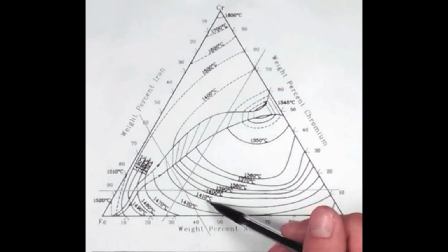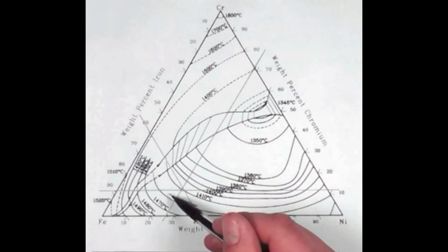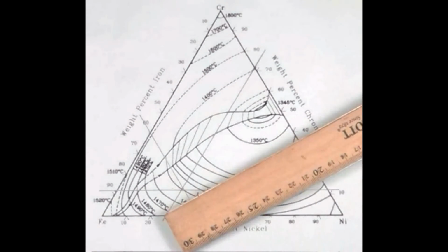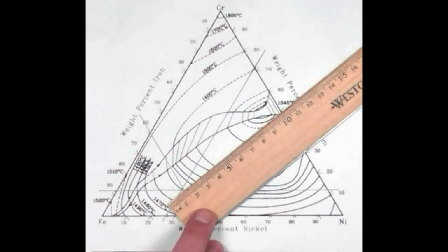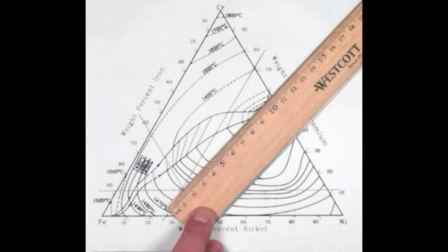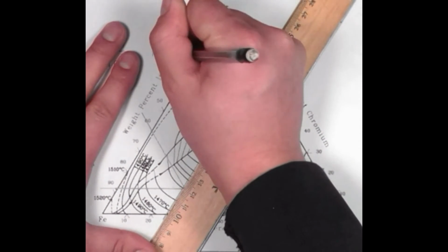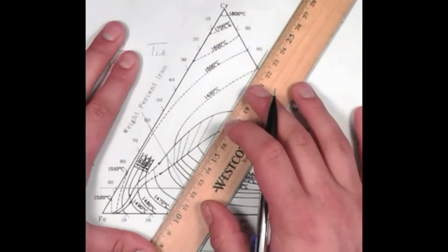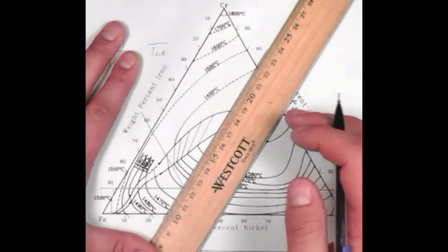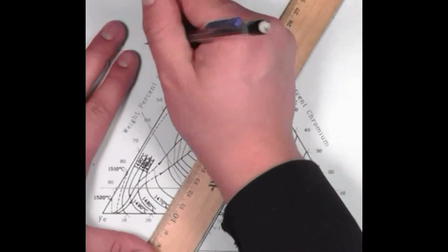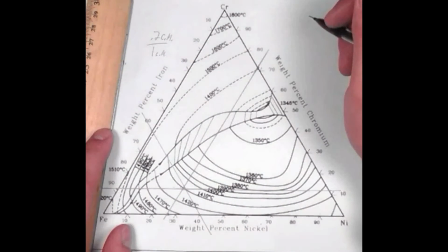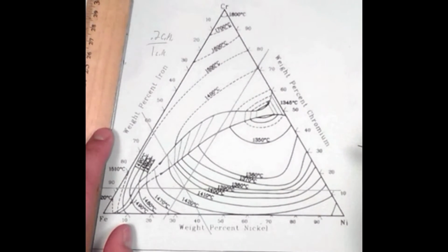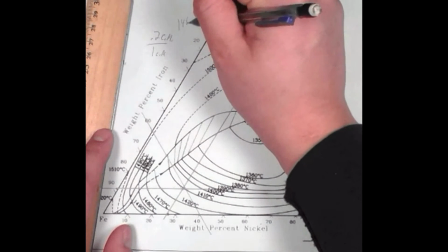As you can see, we were slightly over 1410 degrees C. If we want the exact temperature, we'll take a perpendicular line in between these 2 points and interpolate. The distance between our two liquidus lines is 1 centimeter. And the distance between our point of intersection and the 1410 degrees mark is 0.2 centimeters. Therefore, in order to obtain the desired stainless steel, we will need to heat it to a temperature of 1412 degrees C.